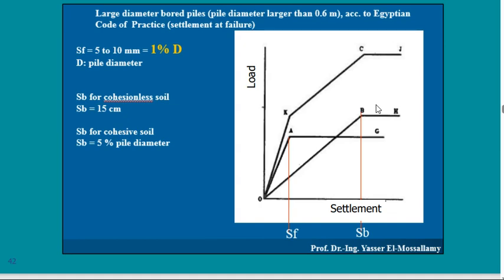After I finish this, what should I compare? I should compare what I got with the structural capacity of the pile. This you do with all methods, because once you reach the amount of load carried by the soil, you have to check the pile itself. Suppose I have a pile made of wood and a pile made of steel. Are they both going to carry the same amount of load? The soil around them will carry the same, but the pile itself cannot.